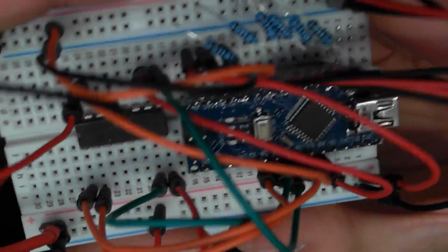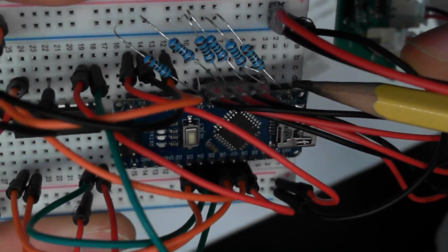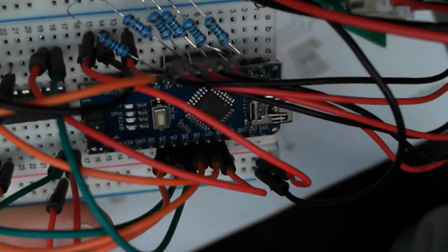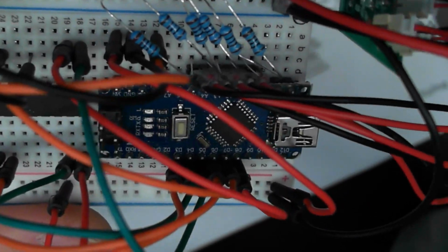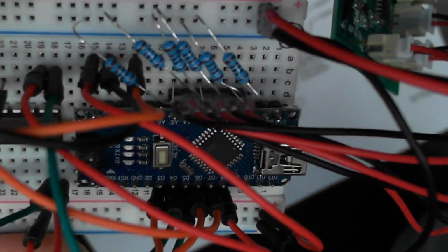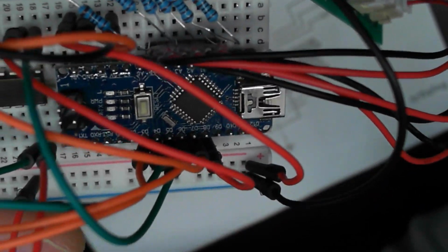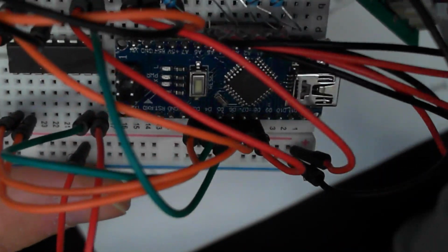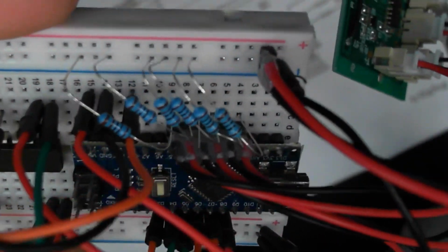One thing to note is that we don't want any of these leads here to be touching each other. Since these are independent signals, we want them to have their own independent paths to the Arduino. If they're bridging, it's okay, nothing's gonna fry, but if you only wanted one signal to be active, it may turn on a different signal, which might activate some other thing. So let's say you're trying to go right, it could go forward, it could go backward and forward at the same time. So just make sure that all these pins are isolated and just away from each other.